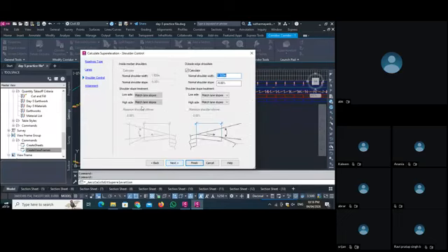Then next, the shoulder control. See, now the normal shoulder here, I will provide our slope as 2, and I have the width as 1. Then I set this criteria as per the assembly we created. The same thing, if we have left and right, we can set it also here, but we have both the same.